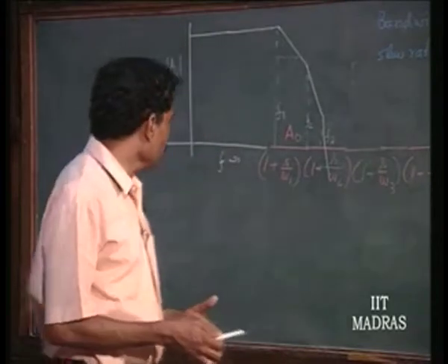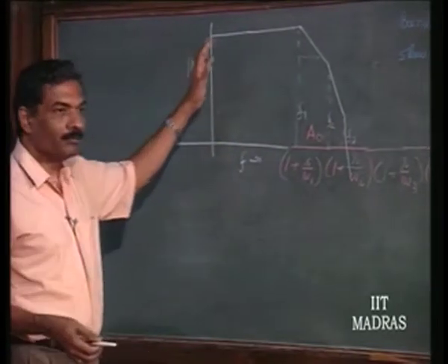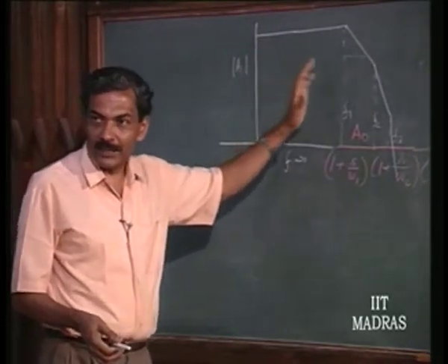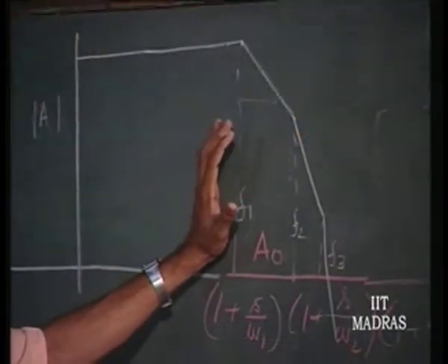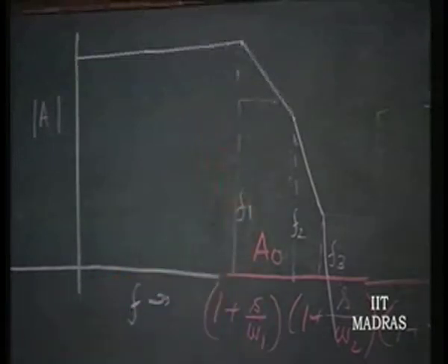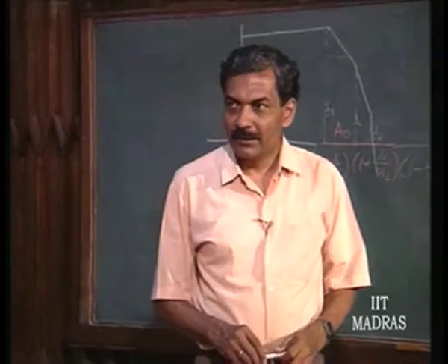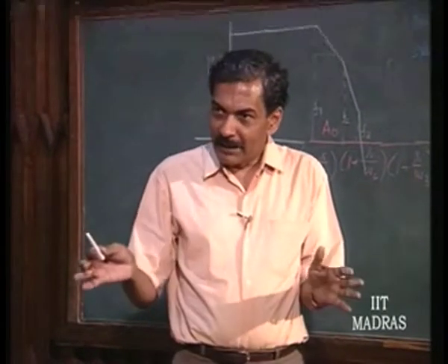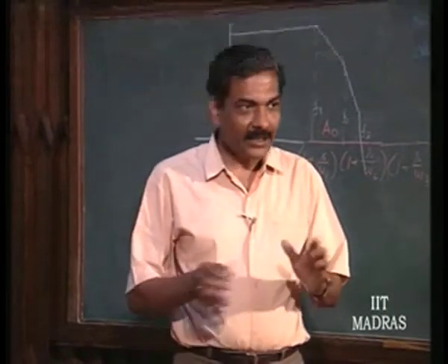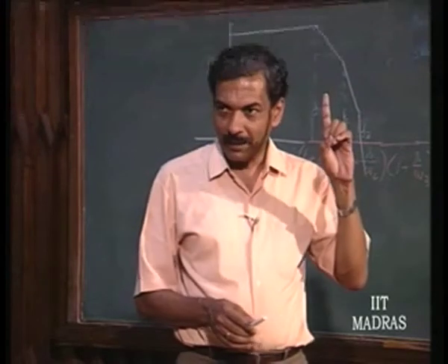then it will start oscillating in that negative feedback situation, right. So, if the loop gain, that is A into beta, is still greater than 1, then there is a possibility of it oscillating. If A into beta, beta is the feedback factor, is less than 1, when this 180 degree phase shift occurs, it is not going to oscillate. For all values of beta, if it is to work, then the worst case value for beta is 1.